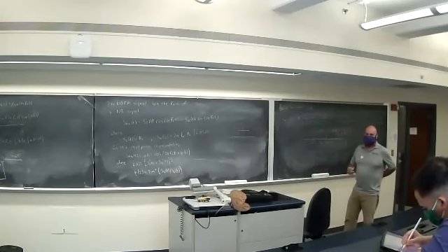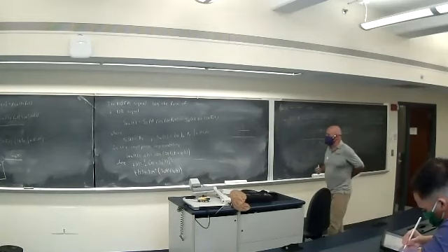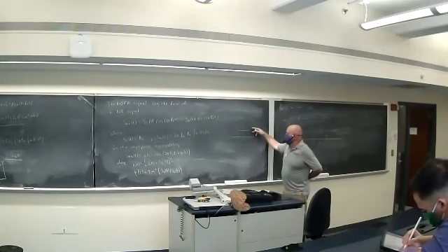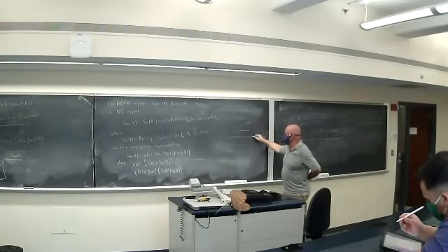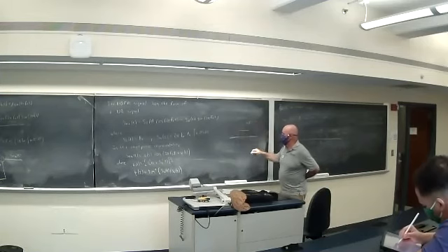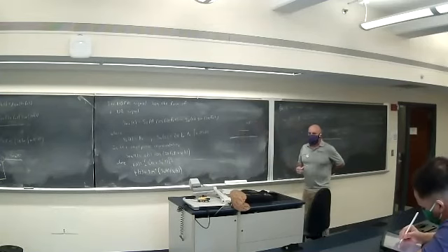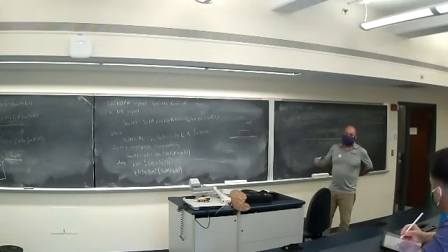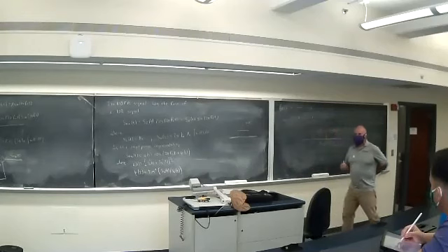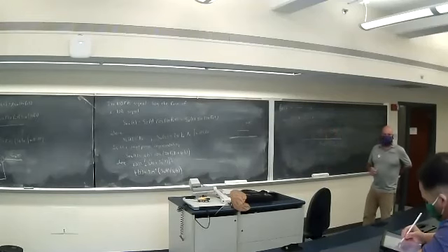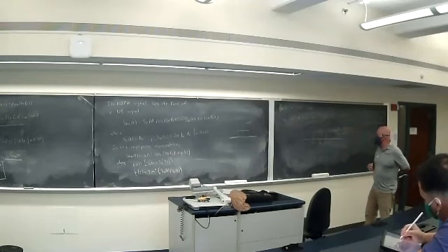So if this is M of f, which is 0 out here, the bandwidth of the integral will be the same as the bandwidth of the message, because it's 0 outside the bandwidth. So there's no change there, and the integration doesn't increase or decrease the bandwidth. Neither does differentiation.